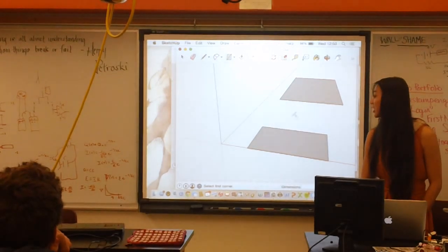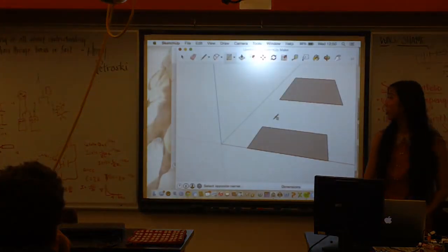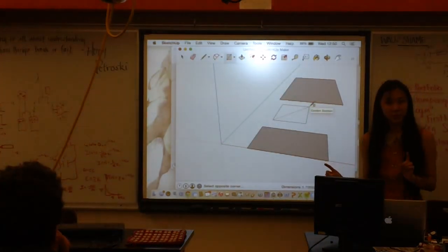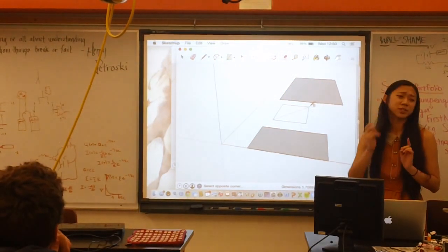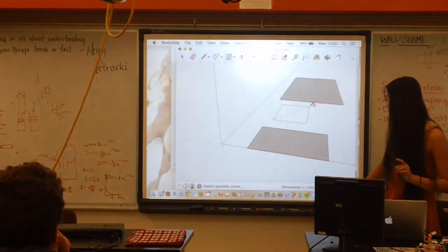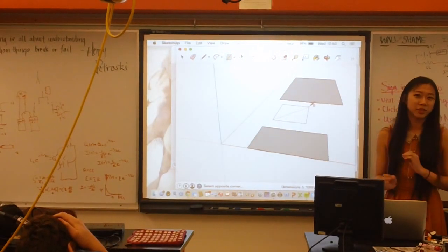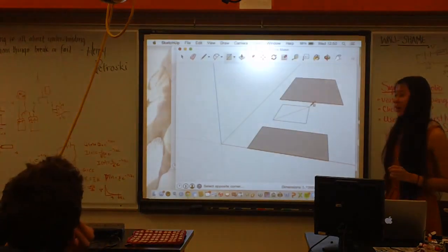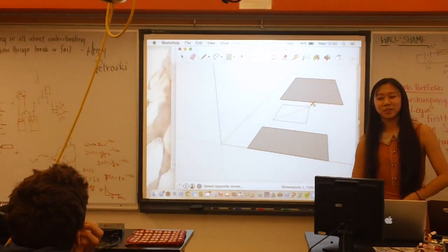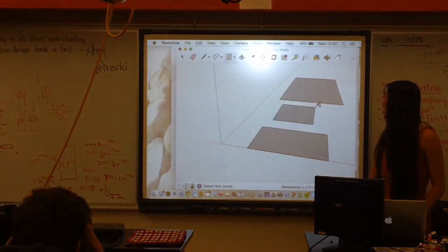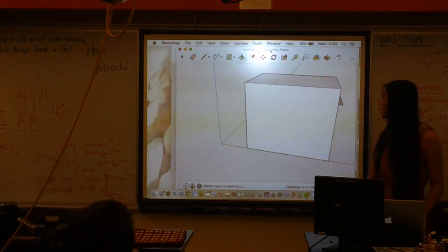Well, if you find that you're trying to change the dimensions afterwards and it's not working, it's because the setting is such that you need to draw a point, and then before you click on the second point to finalize the shape of your figure, you need to type in the new dimensions of your shape. And this text box will accept anything that you enter whenever it's relevant. So be careful about accidentally typing in numbers when you're drawing things, because it might just make something you don't want to make. Okay, and then this is called, I've already shown you guys the push-pull tool.